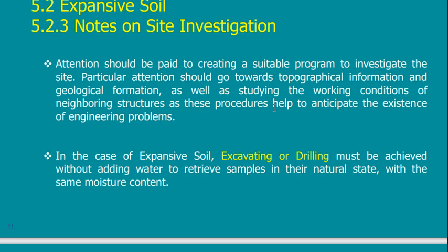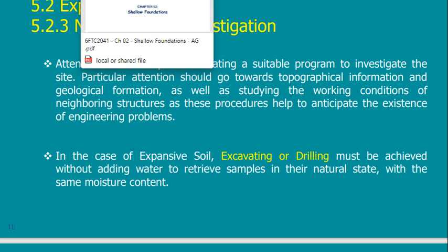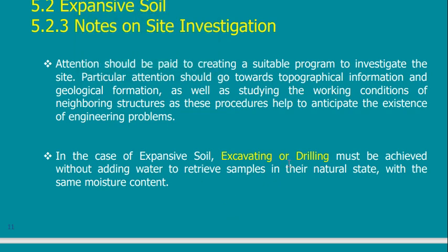I will take these samples to the lab. The lab will not discover any problem and will tell me the soil is very good. So I need to define a very good site investigation program to take a sample in its intact condition and take it to the lab to study it, or the opposite, to study it on site, to make some investigations on site.